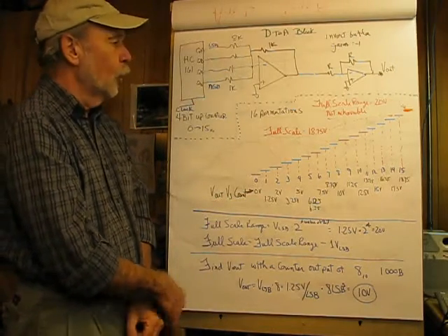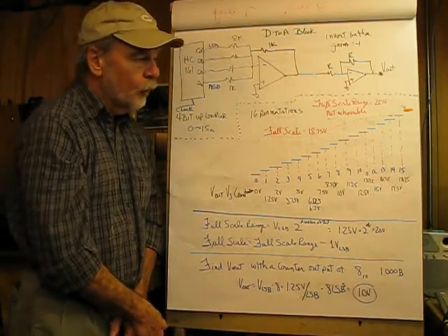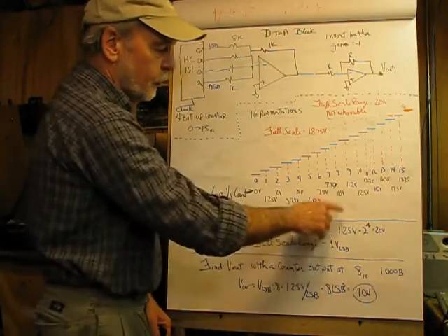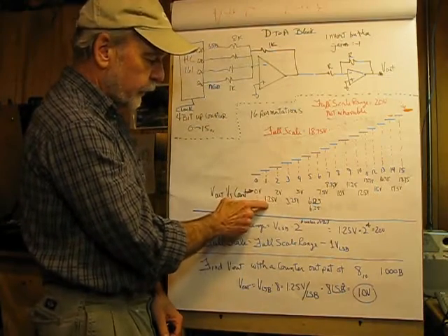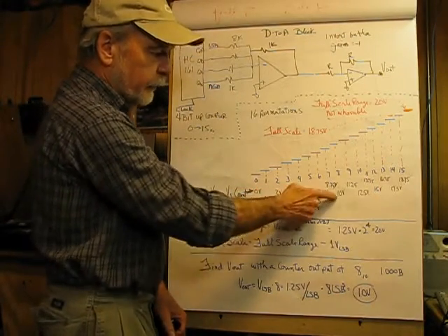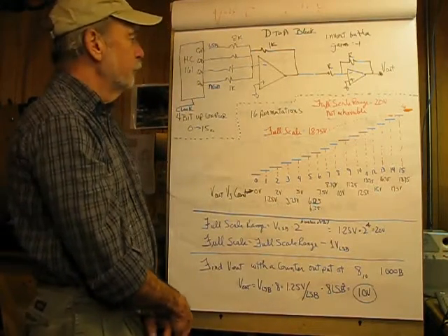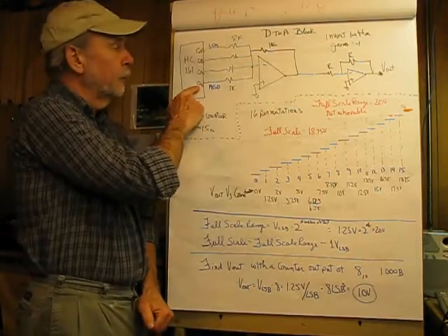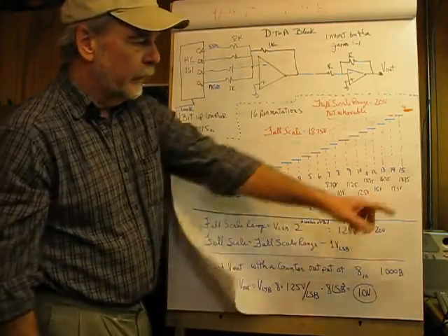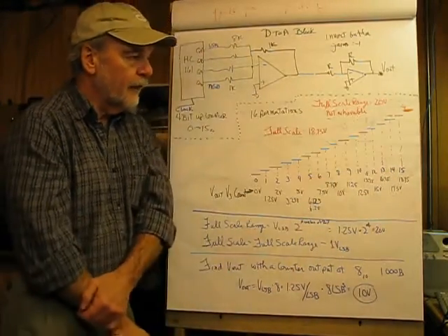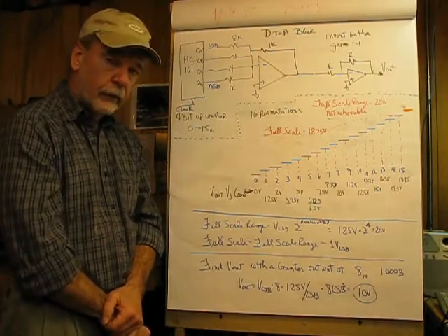And then finally, when the count here is all 1s, in hexadecimal that would be F, we're going to be sitting at our maximum output, which would be the sum total of all of our bit weights: 1.25, 2.5, 5, and 10 volts. Those would be the respective inputs for QD being the most significant bit and QA. When all of these are binary 1, we end up with 18.75 volts, and that's called the full scale of the converter.